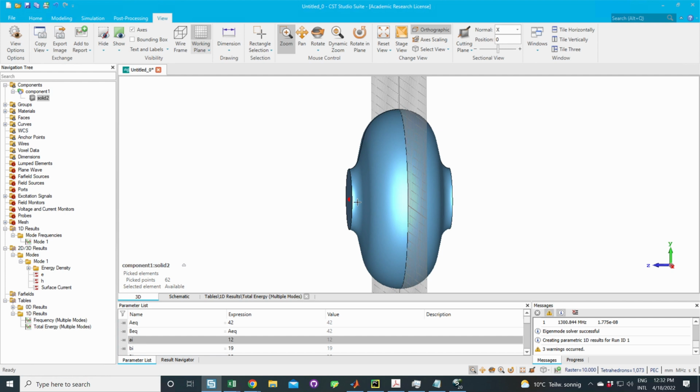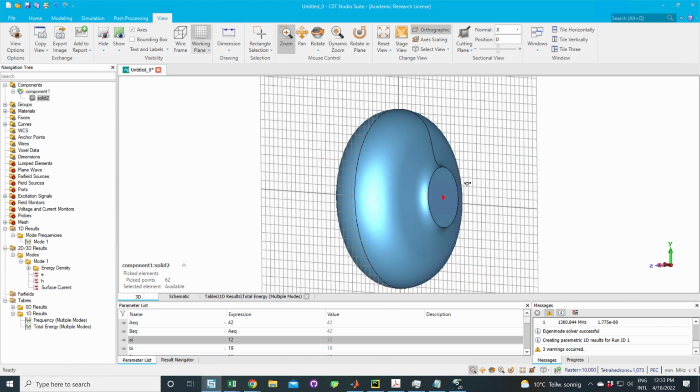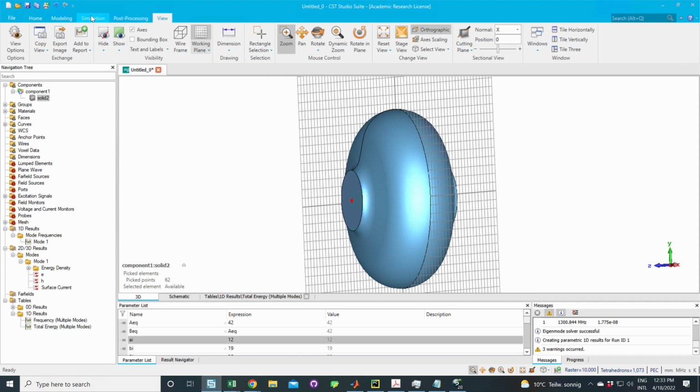So how to evaluate? What we're interested in is the peak surface field, the ratio of the peak surface field to the accelerating field. We're going to calculate the accelerating field later, but since we want to evaluate the peak, which is the maximum electric field value on the surface, we have to create a surface. We could create a surface, a line, points, whatever we want. And how do we do that?